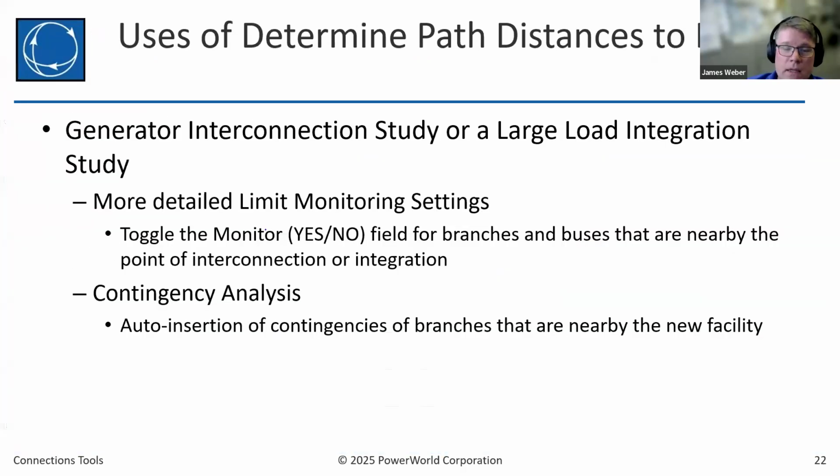The advantage of a tool like this, the thing that I do see our customers use this for, is a customer doing a generator interconnection or a large load integration study. Sometimes they're like, hey, I want to monitor things that are nearby. So they'll start by saying, I'll just monitor things in my area or my zone or something. They'll just filter in that way. But they might want to say, I just want to monitor anything that's within 10 nodes of mine, or this summation of impedances away from mine. So they can do this to populate that custom float field.